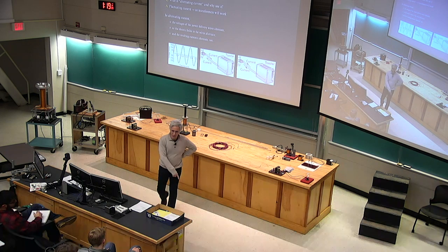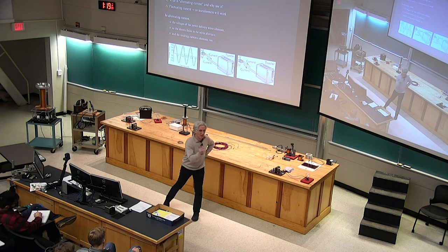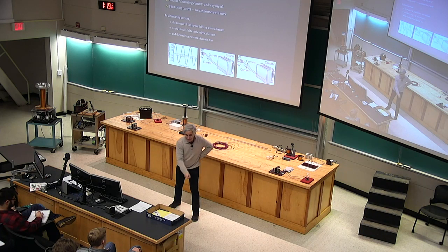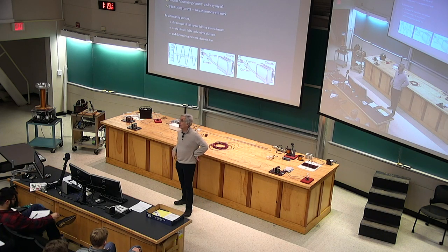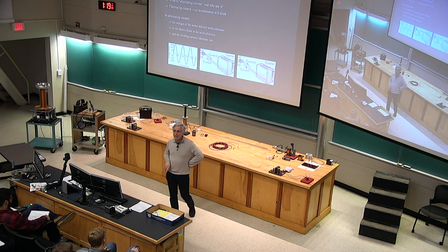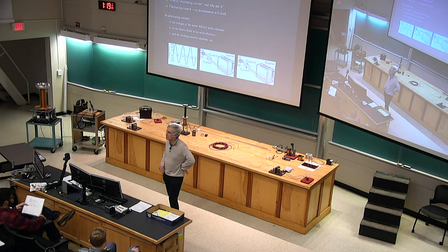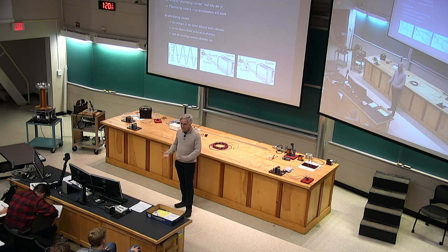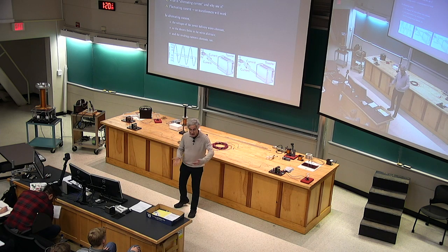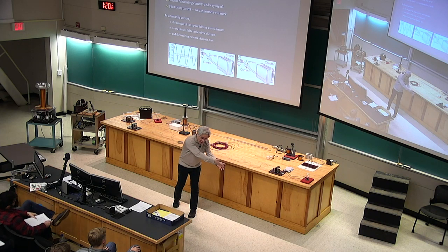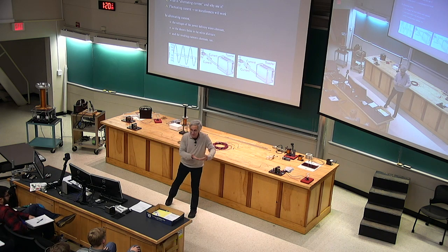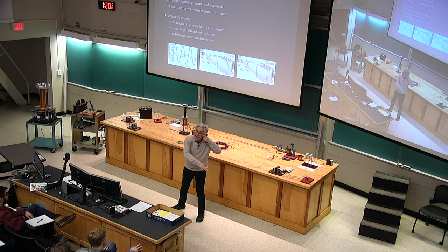Whereas direct current means the current is always going the same direction through a circuit, and typically, not only is it the same direction, but it's the same amount of current, nothing's changing. In alternating current, that's not true. In alternating current, the direction in which the current flows reverses periodically. Typically, the reversals are very smooth, and the current goes first one way, slows to a stop, then goes backwards the other way, gets faster and faster, and slows to a stop, turns around, goes backwards faster and faster, and slows up. It's smooth back and forth.